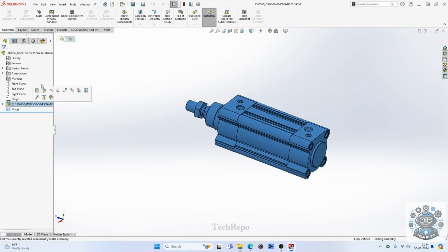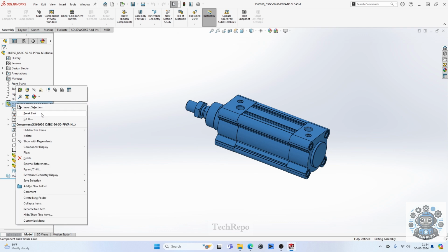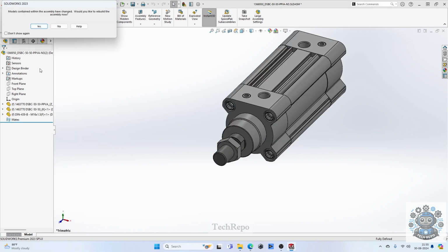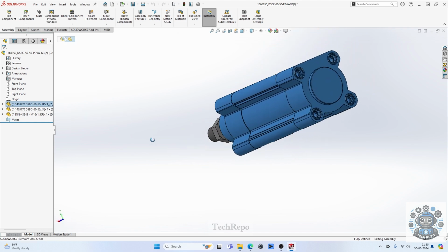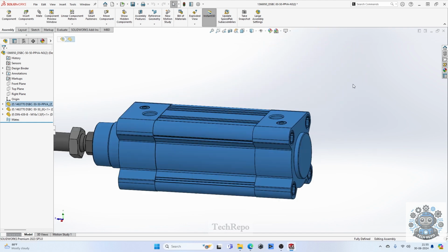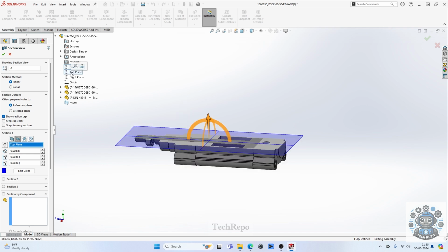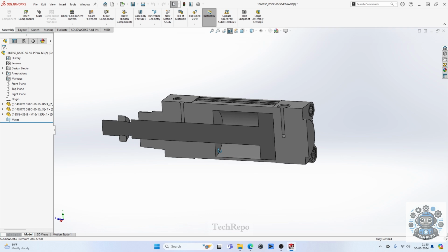Next, one important thing that you have to do is, if you click here, you will not be able to see Open. The reason is that this is linked to the STEP file. The advantage it gives us is that if you bring in another STEP file, dropping into the same location, this would get updated. But practically, it hasn't been much useful for me. So we always break the link whenever we do a design.